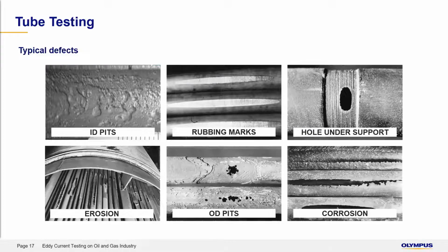And these tubes are made of different materials and designs. For example, some are made of non-ferrous materials like aluminum, copper, and Muntz brass, and some are of ferrous materials like carbon steel, and some also have fins, etc. Tube inspection generally makes use of techniques such as eddy current, remote field, near field, magnetic flux leakage, and ultrasonic for the inspection. These methods are typically only available in advanced testing equipment, which sometimes tends to be overkill for, for example, small HVAC systems.